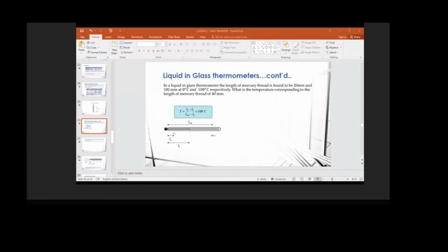All right, we also have the resistance thermometers. All right, so it uses resistance to actually give you the value of your temperature. The advantage of these is that the sensor can be easily installed and replaced. It's good measurement, it has good accuracy, because temperature varies with resistance. Very, very good. Right, so the accuracy of these thermometers is very good. They have fast response and good productivity.